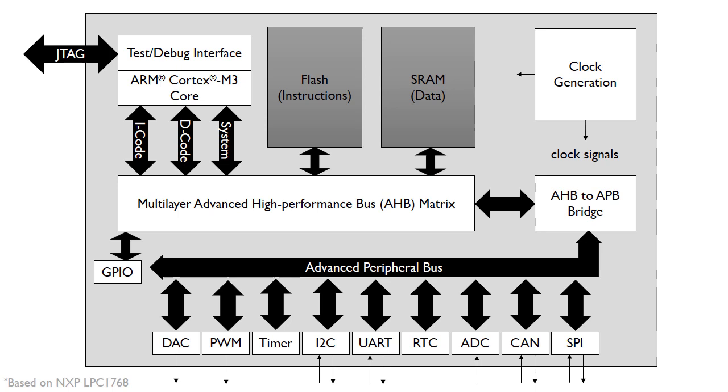So look at the block diagram of the microcontroller. Inside, we can see they've got the core, which is like the CPU. We've got our flash memory where we're storing instructions, and our RAM where our variables and so on will be stored in the code. And then we've also got these peripherals connected via this bus system.